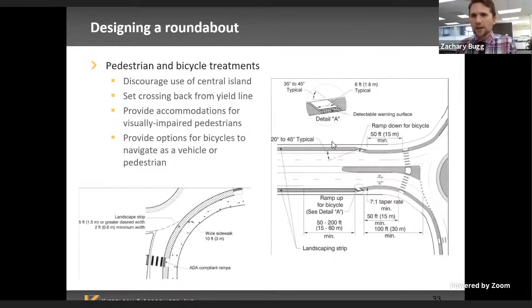Vehicle speeds are much lower through a roundabout. They're comparable with typical cyclist speeds, again, 40K or less. Or cyclists can take a ramp up into the path system and cross the roundabout legs similar to pedestrian movements. And then there's the mirror image of this on the other leg, where they would be able to go back into the bike lane. Seeing some concurrence with that.